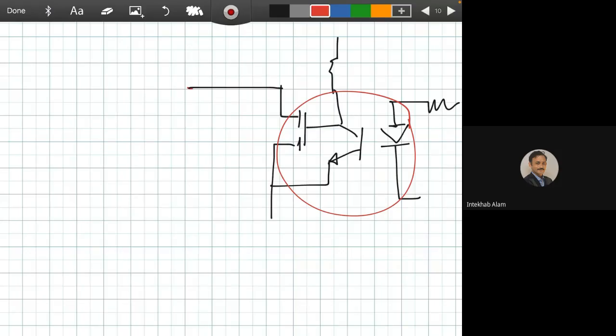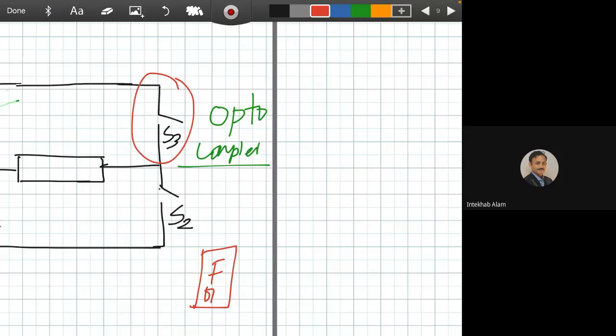It's your circuit. There are four switches in here. Switch S1 and switch S3 require an optocoupler. So you have to place those optocouplers properly using MOSFET and function generator, but you have to use only one function generator.